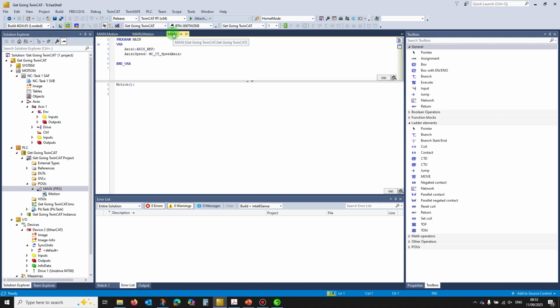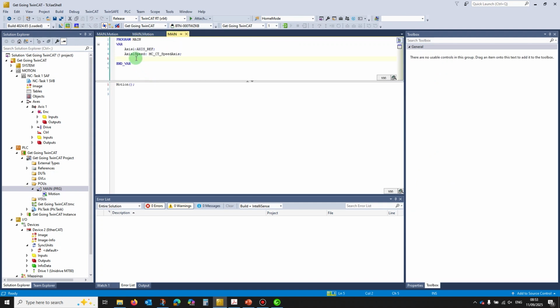So the first thing that we need for an NC axis is to map up the PDO in order to transfer the velocity feed forward reference. Unlike a CNC axis, where this step is kind of done for you, unfortunately an NC axis doesn't have the ability natively to do velocity feed forward. So if you want to do it, you have to manually calculate it, and it's only 2 lines of code, so it's not too onerous. If you want that extra performance, you basically have to put in 2 extra lines of code. So that's what we're going to do now.